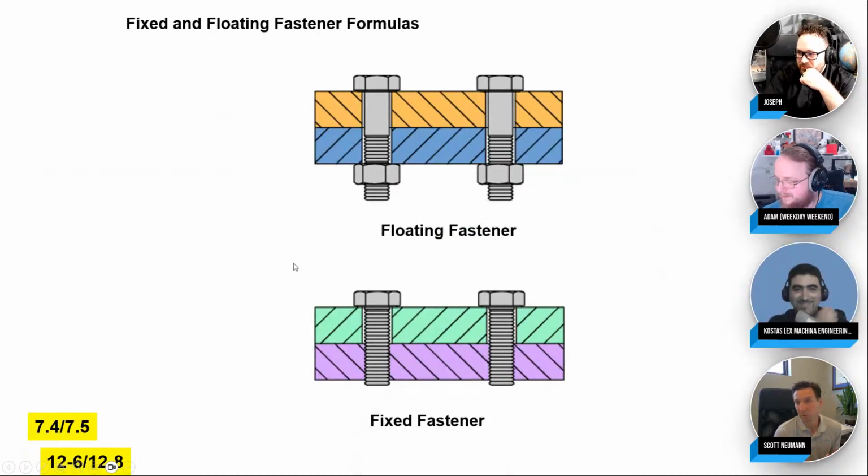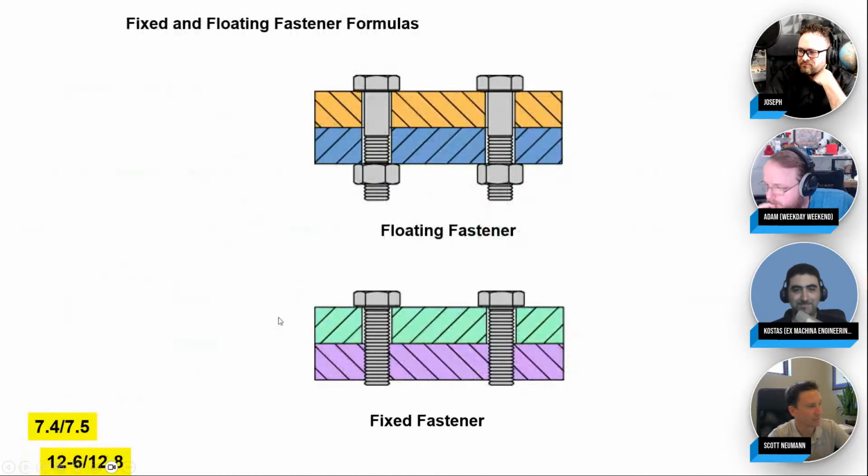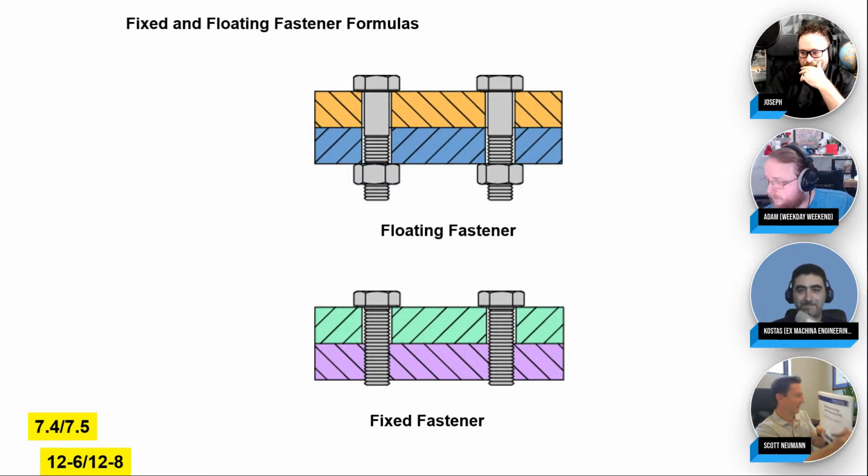And so now people understand what position tolerance is and how it works. Then I was thinking about showing you how to calculate the value. That's kind of the big question people get. They're like, okay, I understand position tolerance, but how do I calculate the number? What number should I put on my drawing? Especially for clearance holes for bolts and fasteners, we have some great formulas in the standard. This is in non-mandatory appendix B of the standard, taking the information from there that's been passed down since the 1950s and putting it into a lesson for us to learn here.